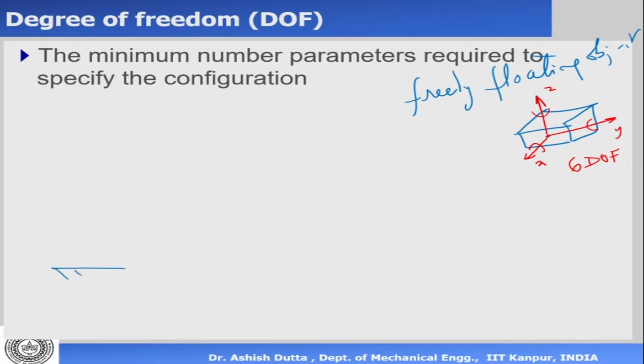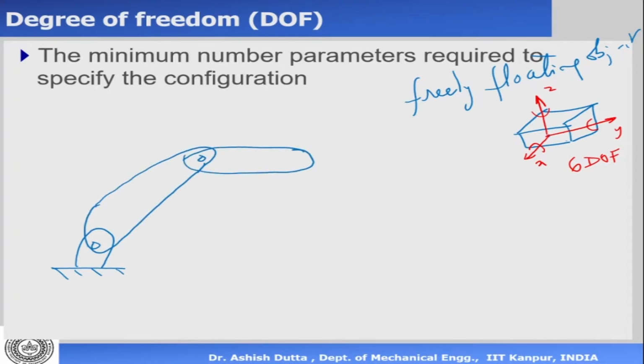So this is fixed at the base, it doesn't move. Then we have the first degree of freedom of the first joint. This is the second joint, and that's my third joint. This is my second joint. Okay, so this is my fixed joint, and the variable here is theta 1. The variable here is theta 2.